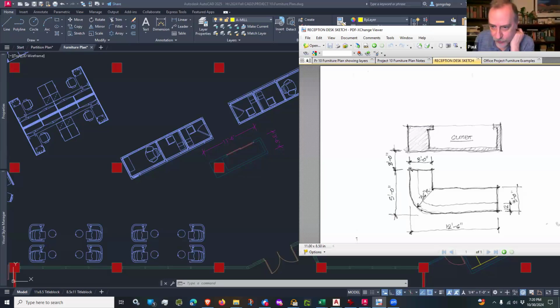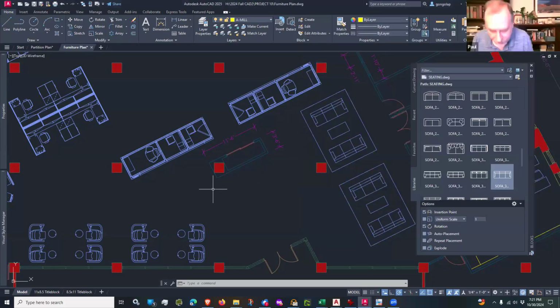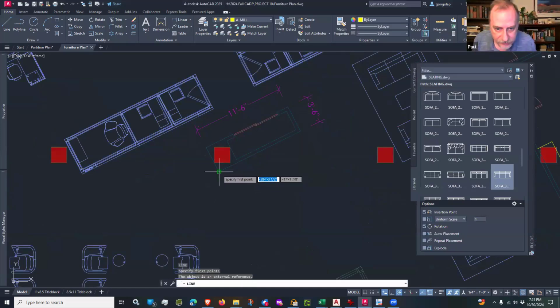And so I'm going to O-track over 3 feet, and then I'm going to draw a line 5 feet long by 12.5 feet. I'm going to come back 3 feet, come over 3 feet, and then fillet these lines, and then I'll draw a radius. I'll do a fillet with a 36-inch radius. So that's how I'm going to draw this puppy. So let's give it a shot here. So line tool, and I will start here, and let me put my O-tracking on, and let's hope that I can O-track.